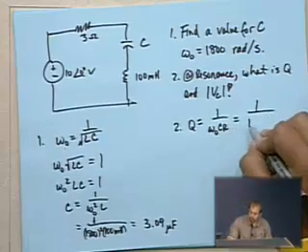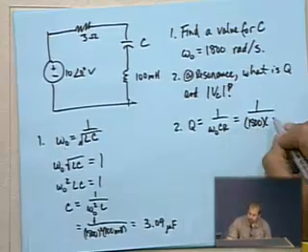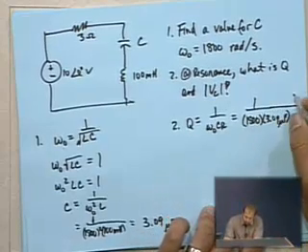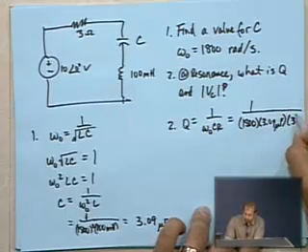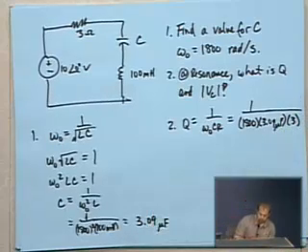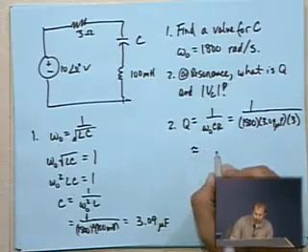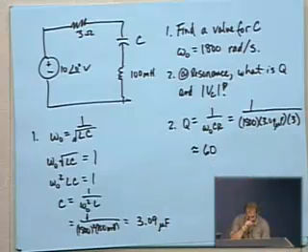So that's 1 over 1800 times 3.09 microfarads. And the other one is the resistor, which is 3. So 1800 times 3.09 e negative 6 times 3. Flip that. Yep. And so that's approximately equal to 60. The answer that I got is 59.93 whatever, but that's the quality factor for this circuit. You should be able to get that if you plug in the other numbers as well.